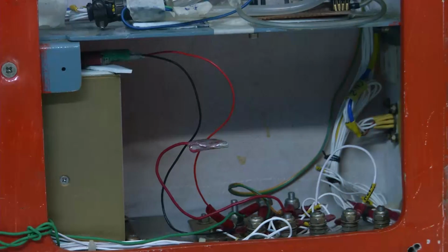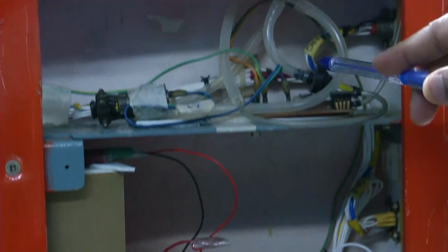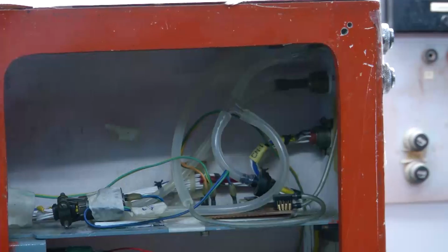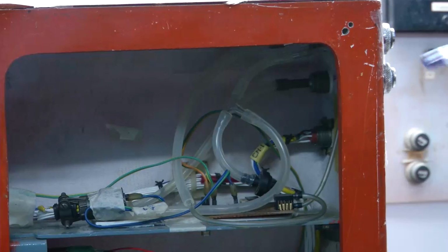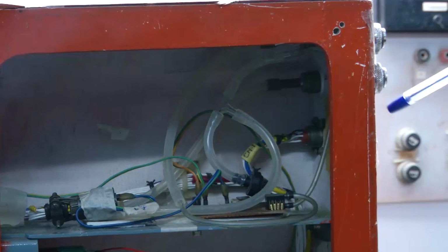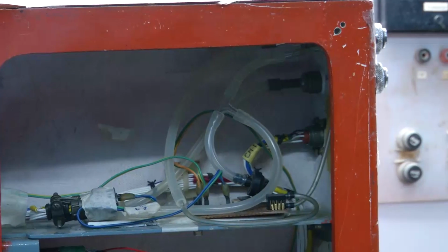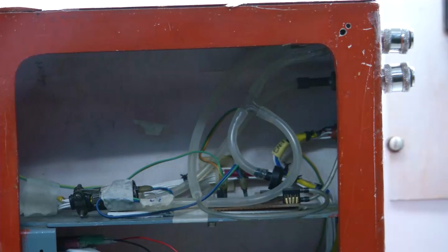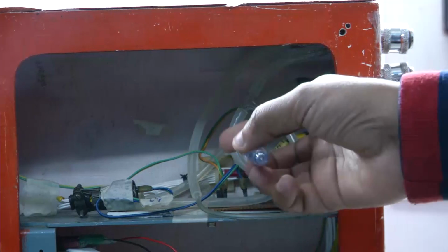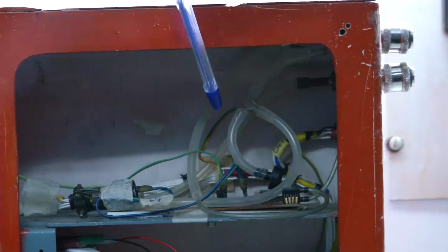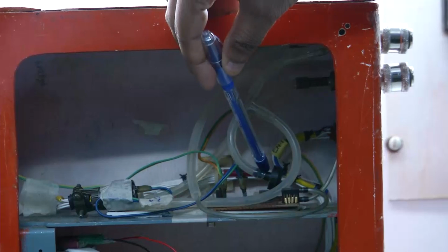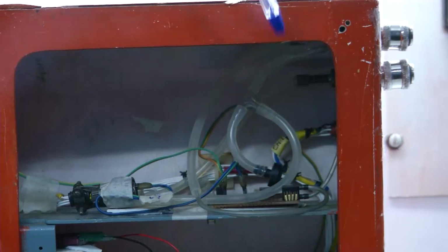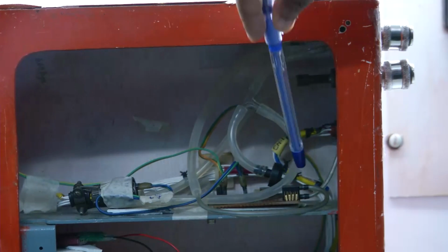And you can see there is a pressure sensor, and in this FDR there are two probes, 1 and 2. These correspond to your absolute pressure and differential pressure. Now these two probes will be connected to probes of the aircraft, and corresponding to that you will be getting an absolute pressure and a differential pressure.